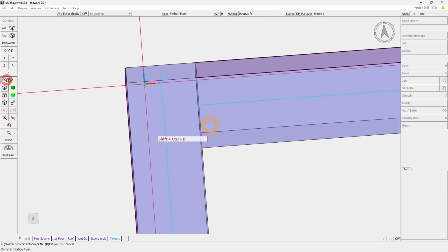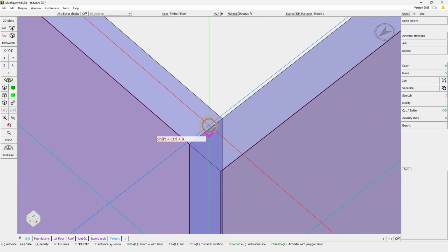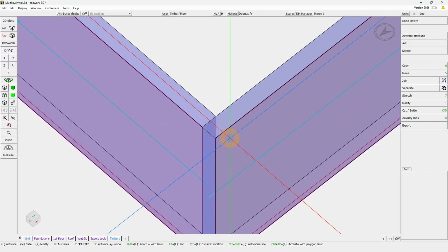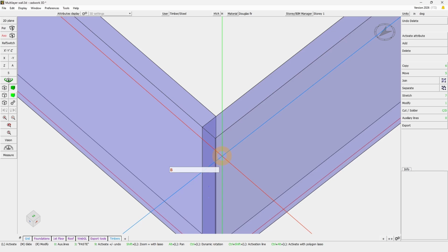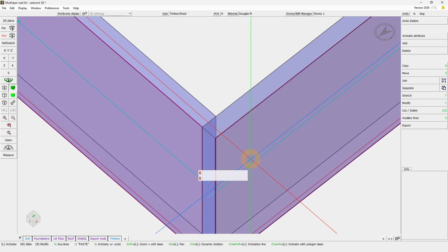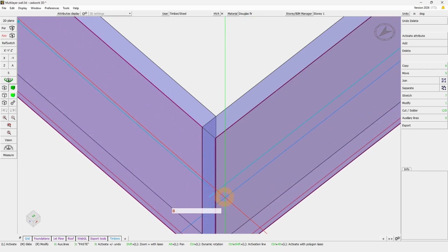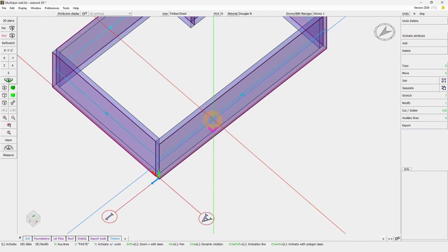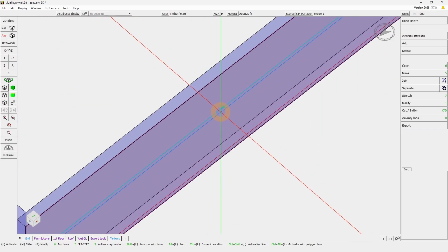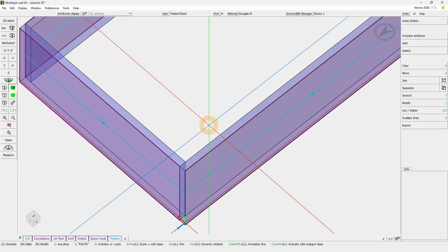If you are familiar already with walls, floors, and roof in Cadwork, you also know that by pressing B, you will hide or display the reference face and the wall axis, showing in this case the framing direction for those of you using the element module.